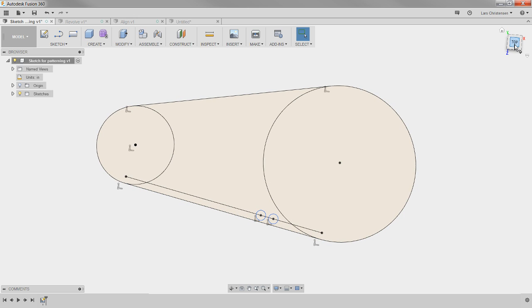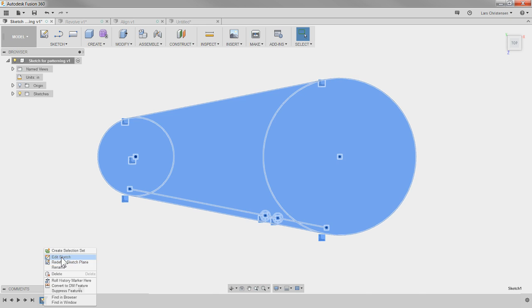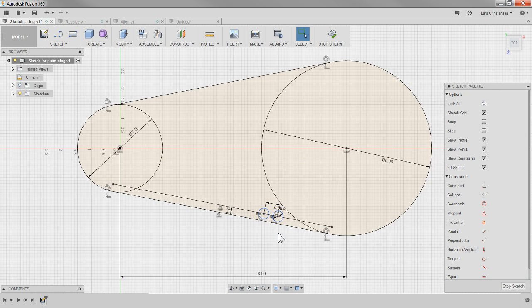Well, what Stefan's talking about is he started drawing up these circles. When you're doing a dust collector for a router, there are kind of like these brushes that go all the way around. He's going to put the holes in there. But of course, if he wants these holes all the way around here, it's going to be a little bit of a pain in the neck to do that, right? So patterning would be a good solution.